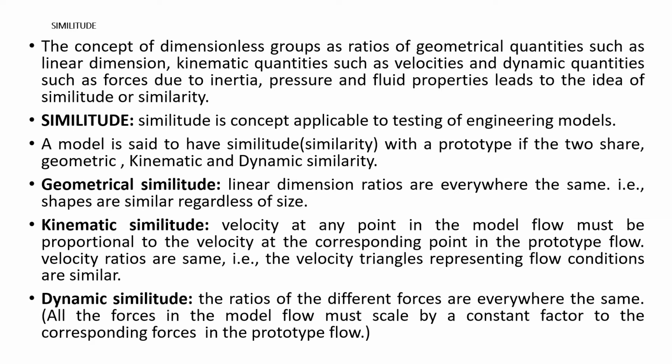And the last one is dynamic similitude. The ratios of different forces are everywhere the same. What do you mean by that? All the forces in a model flow must scale by a constant factor to the corresponding forces in the prototype flow.